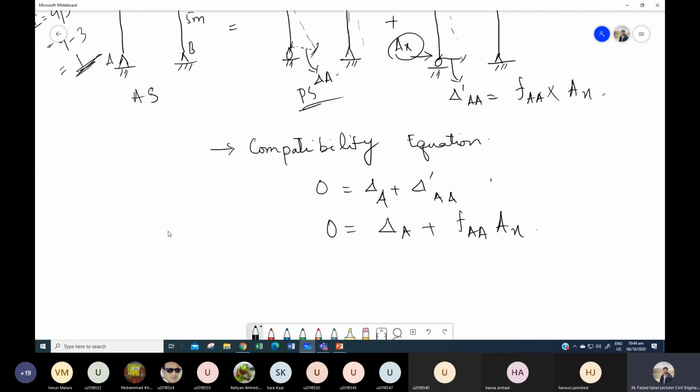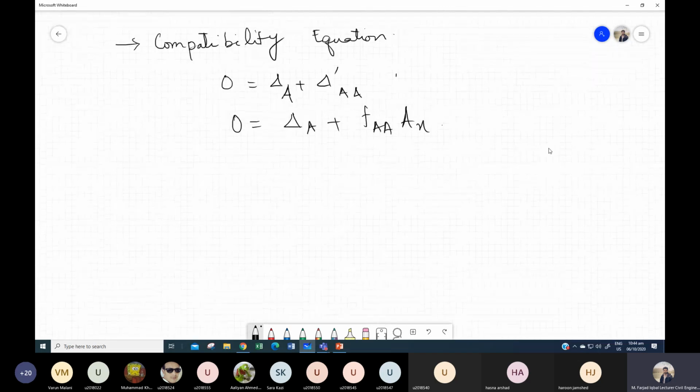In the case of a beam, we can figure out these deflections directly because we have some direct formulations available, but this is not the case in frames or trusses because every frame or truss has different kinds of loads acting or different support conditions. So we need to figure these out using some method. I'll be using the method of virtual work in most of the cases. You can apply some other method if you feel convenient; it's not compulsory to use this method.